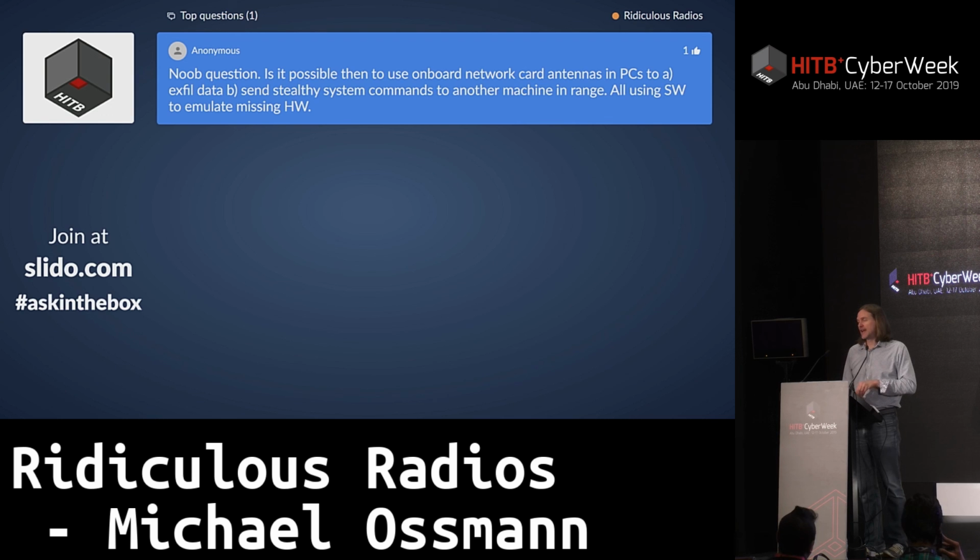In some cases, yes. An example of that, I would say, is how we were able to take this off-the-shelf Bluetooth device and get it into a test mode by telling its firmware to generate a test signal instead of telling its firmware to generate a Bluetooth packet. And so that's an example of how we could implement just an on-off keying transmitter using this Bluetooth device that could be embedded inside a PC.